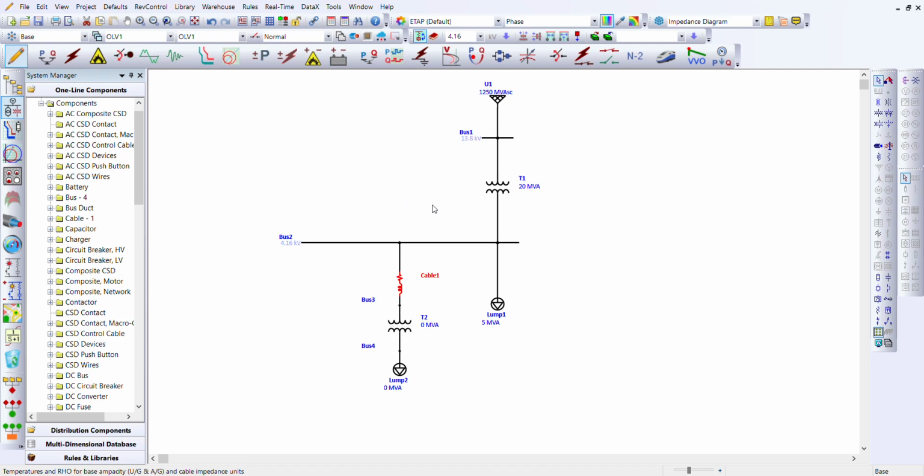Now 3-core, it's supposed to be a 3-core cable, and this is 3-core. Okay, that's good. Then it's supposed to be EPR with the insulation type EPR. That's good. It's supposed to be magnetic. So EPR, but we are forgetting something. NEC. It says the source should be NEC. The cable source should be NEC.